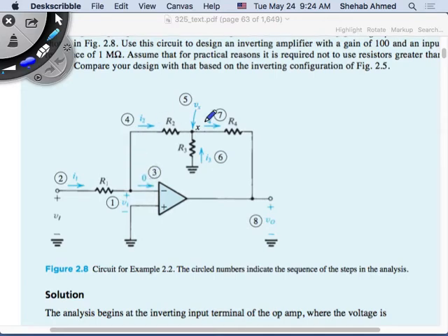If I have negative feedback, what does this imply? It implies that the voltage between these 2 nodes is the same. Here it's 0, meaning the voltage here is 0 as well. Which means that the input resistance is still what? R1. The input resistance is still R1. Is this good or bad? I don't know. It's the same as before so far, right?